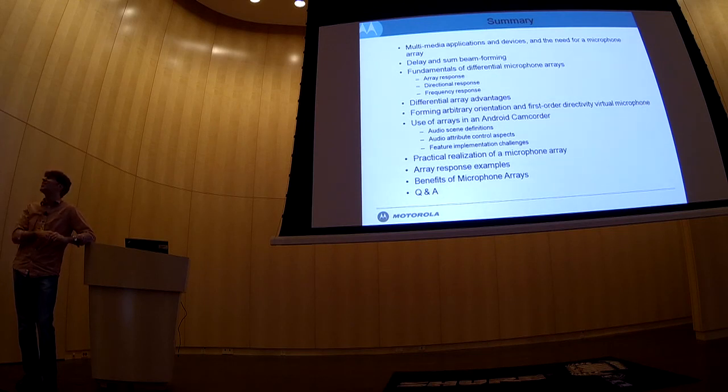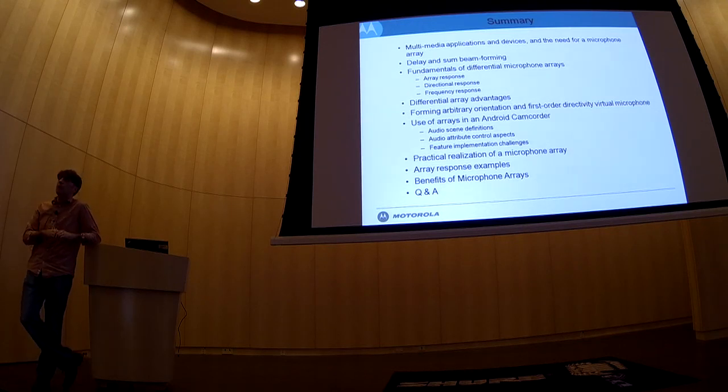For the multi-mic, when you plug the mic, you need to pair that mic. Yeah, the microphone noise, typically we require, well, everyone wants the microphone noise to be as low as possible. In this case, when we do the differential array, because we are losing low frequency due to the differentiation, the lower the noise, the better, obviously. But we are limited by what is available on the market. So put it that way. I don't know if that addresses the question or not.